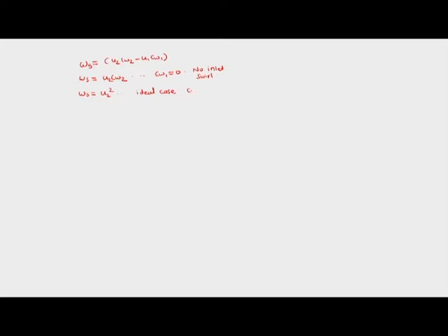Ideal case where CW2 is equal to U2, but it is not valid in general since CW2 is not equal to U2. There is a reason for that, and the reason is called the slip factor. There is a term called slip factor, and this has to do with inertia of the flow. The flow has certain inertia, and due to that inertia it is not going to follow faithfully with the blades.